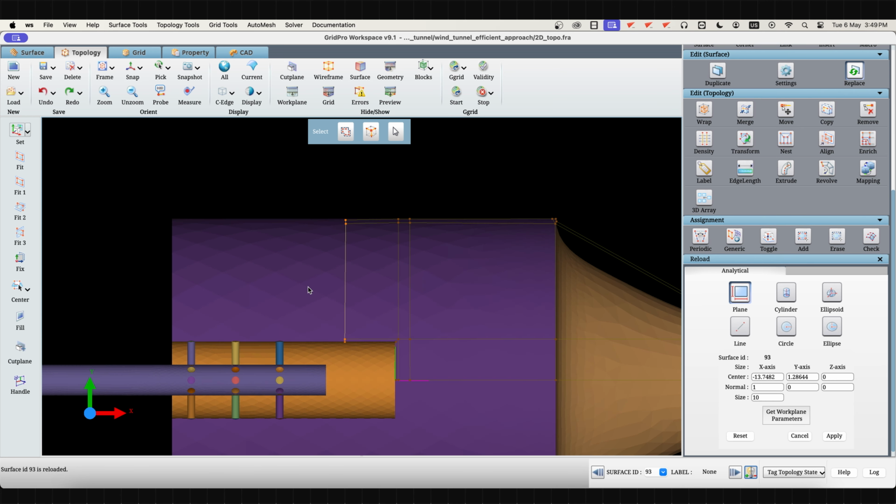Now let's revolve the 2D topology. GridPro's Revolve with Core option helps create core blocking by providing an input corner for the core. Revolve the complete 2D topology about the origin along the x-axis. We need 24 copies of the 2D sheet in the revolved topology, which can be easily merged with the showerhead topology. Group the corners placed along the longitudinal axis in C2, which will be used to generate the blocking at the core.